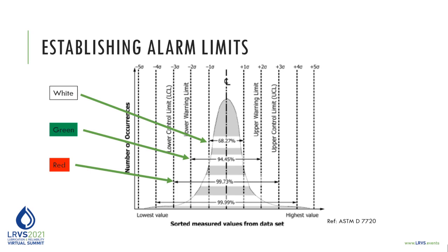These alarm limits can manually be adjusted downward through experience with similar machinery, and in all cases, make sure that the alarm limits are continually reviewed and updated either through statistics or experiences, accessing your CMMS programs, maintenance logbooks, interviews, great opportunity for failure mode effect analysis interviews. The more sample data, the more failure modes and causes are encountered, the better the data is going to be.